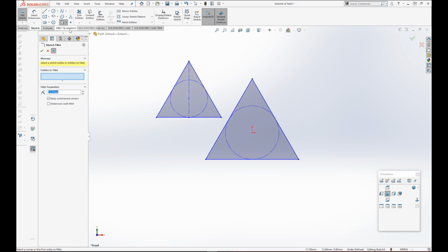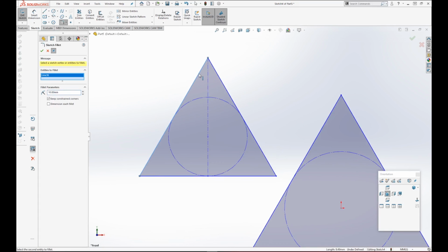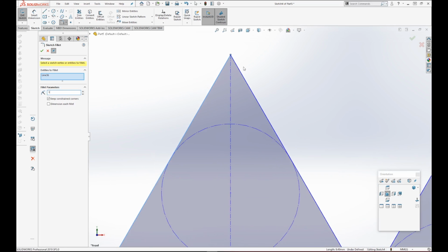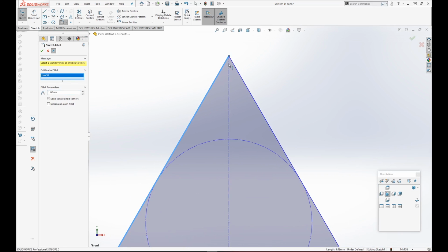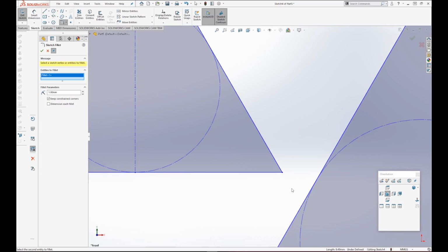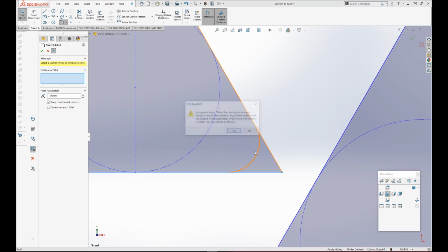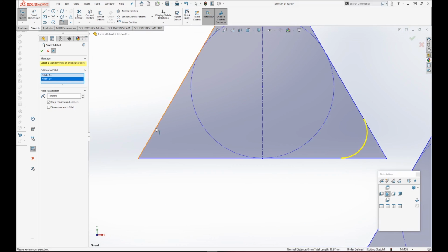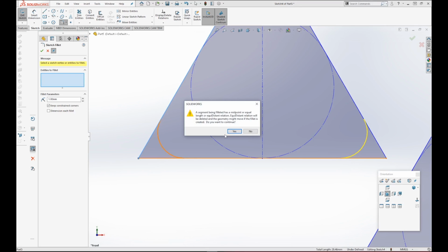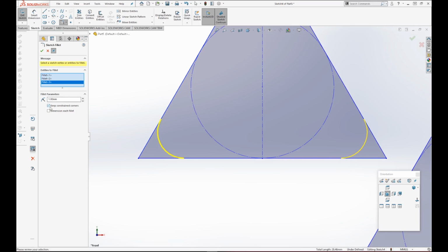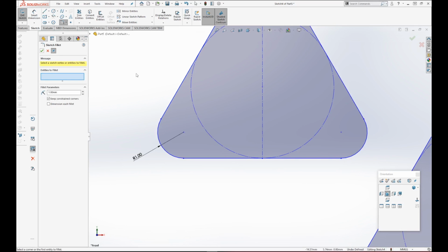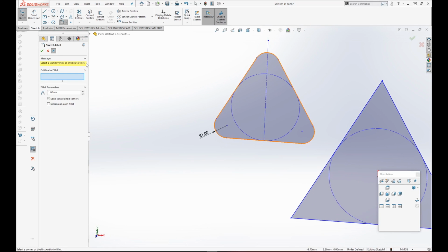This is the sketch fillet tool. How this works is I'm going to select this line, and then I'm going to change my radius right here. I'm going to give it a 1 or a lower number because I think it was a little too big before. Let's do that again. If I select both lines, you guys can see the preview there, it gives me a little radius. I'm going to continue it. I can do it on all corners. Hit this OK. It's just giving me a warning right there. Boom and boom. Then hit OK in the little window. Essentially, it's telling me that my relations and my endpoints are changing. And to finish it all off, I'll click that green check mark right here, letting me know that I'm done doing that.